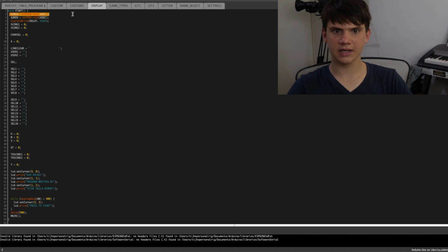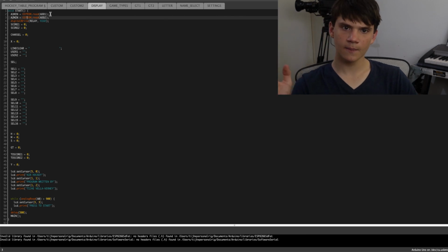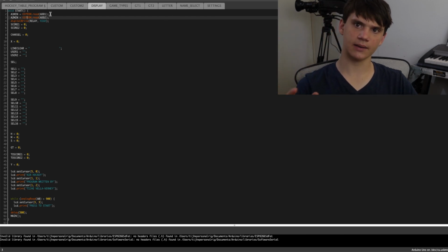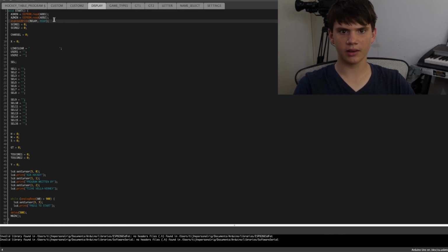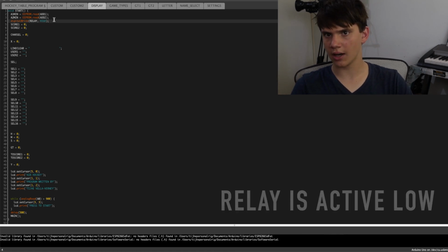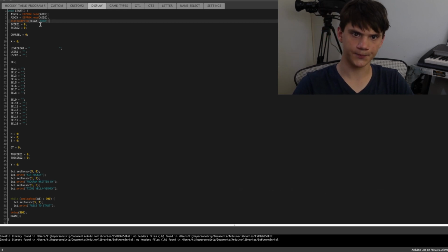So this is where it goes. First of all, it says A1 equals EEPROM.read address 1, as we've seen before. So it's actually going to read what's in that address and then put that as the A1 minimum. It does that for A2, and then it digitalWrite relay HIGH. But when you go high, the fan turns off. When you pull it to low, the fan turns on.